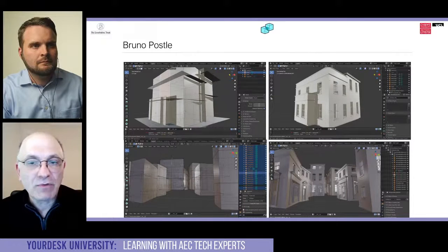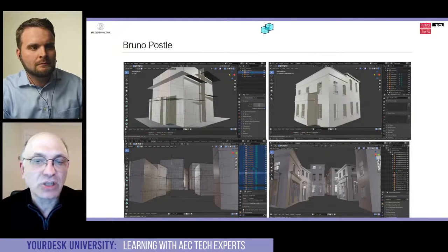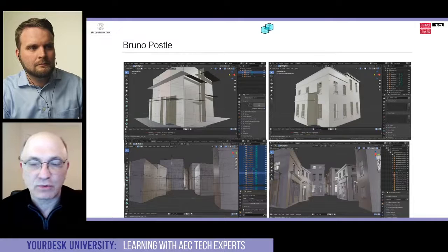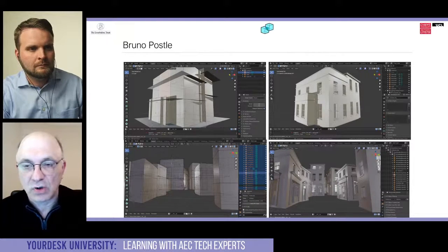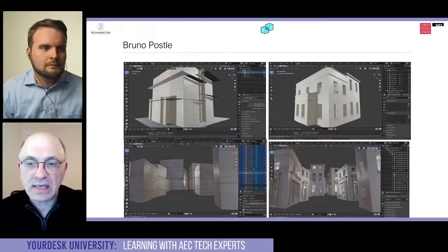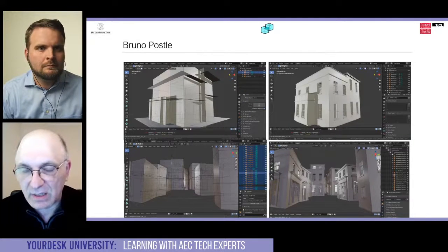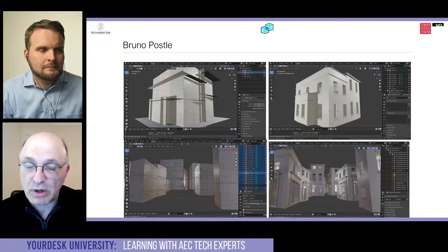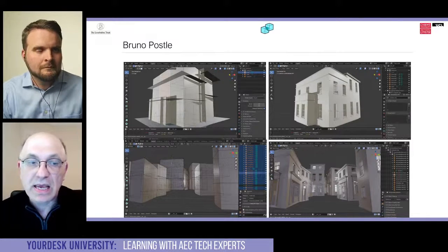It can also have objects that are of different dimensionality. So you can have a cube that has a winged edge inside of it, or an edge or a vertex that's floating in midair, or connected to only part of the face or something like that. We don't make trouble about that. It's all part of the non-manifold topology, and you can find your way through those things.